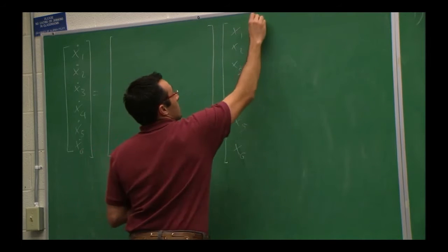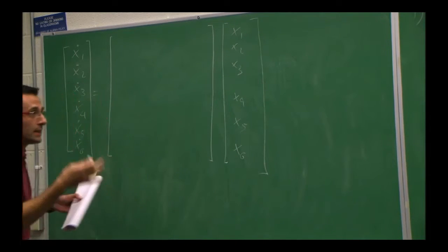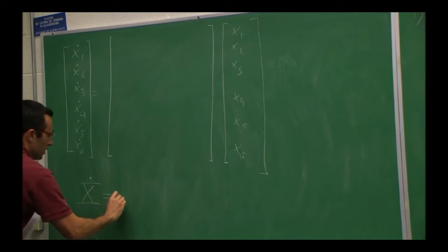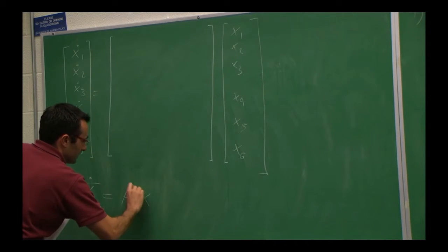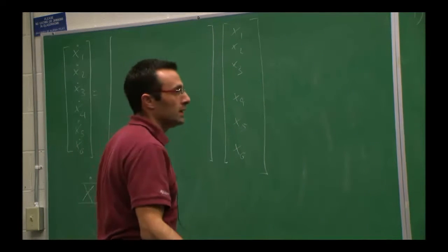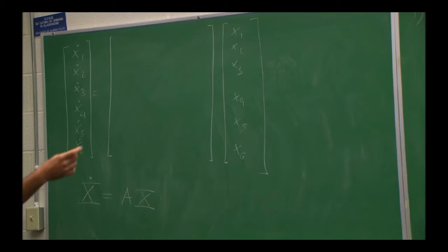Okay? So in other words, what I'm trying to write is that same system in this form: X dot equals AX. This will be your state space representation of the system that uses the state vector, which I have defined that way. State vector is the variables, time derivatives until n minus 1, then you stop, and you rewrite the system the following way.